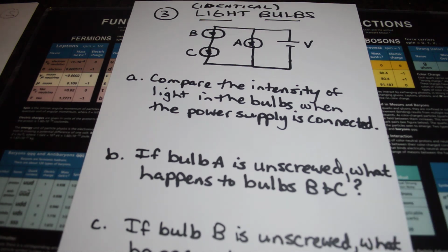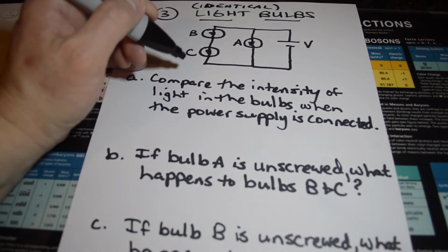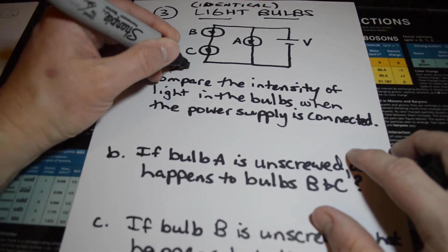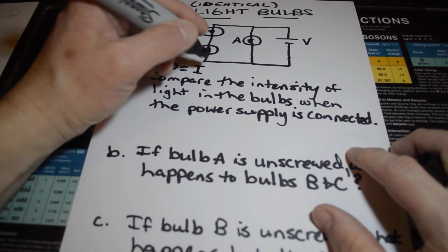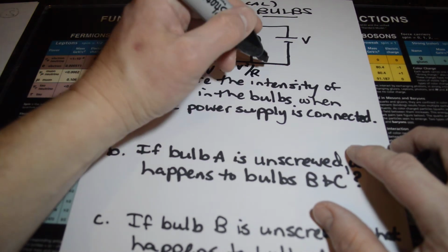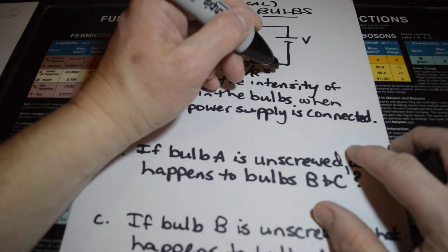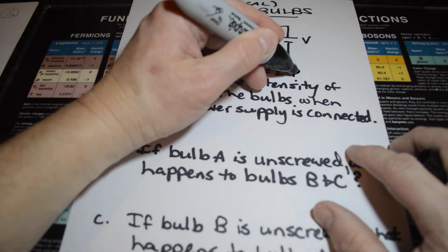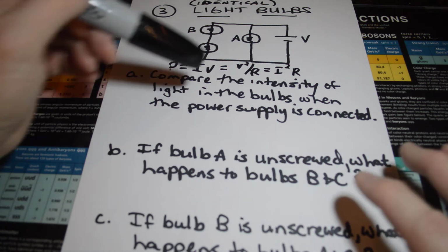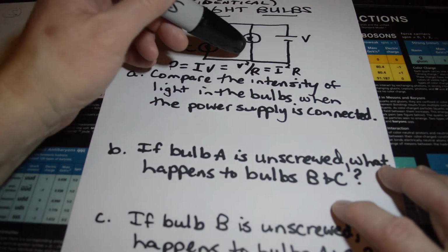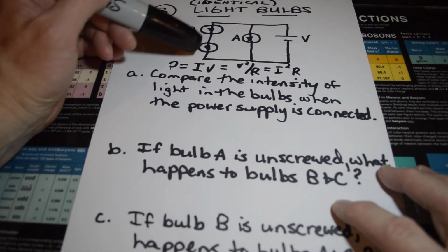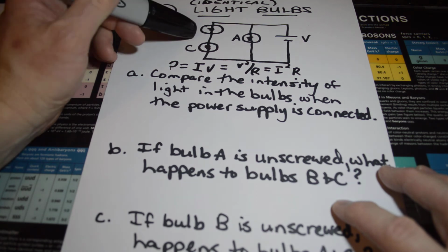But I think it would make sense if you go back to the equations we just had for the last problem. You're interested in the power, which would be the current times the voltage, voltage squared over the resistance, and the current squared times the resistance. Well, the voltage is the same for both branches, but you're going to divide by a greater total resistance. So you're going to have less power for the two in series.